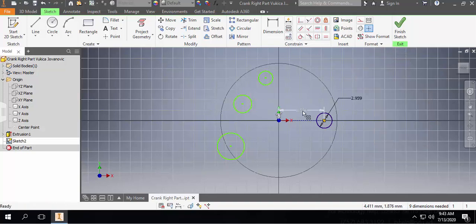coordinate system. And this would be, if you take a look at the picture at 721, this will be 5.25, and the diameter of the circle will be 3. So basically that's how I'm defining something in a polar coordinate system. I'm defining the angle. I'm using the constraint for that, the horizontal constraint. 5.25 is the distance, and 3 is the size.